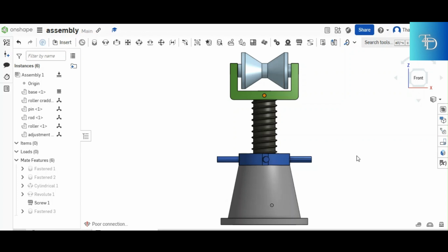So now after being able to analyze what goes where and how, the next thing you do is you just start drawing. But when you draw the parts, remember, you don't draw the outside views, you draw the sectional views of the part. So we've already solved the sectional view of the base. So let's go solve the sectional views of the other parts.